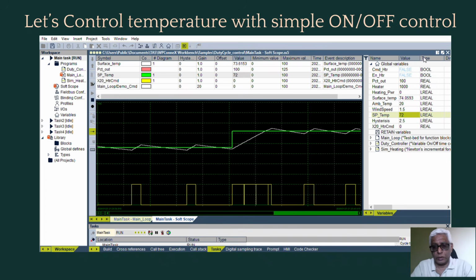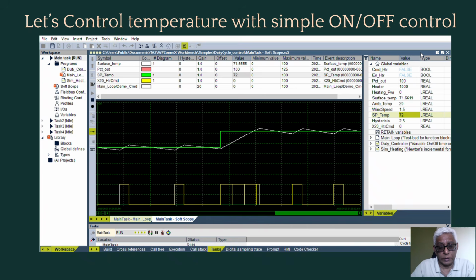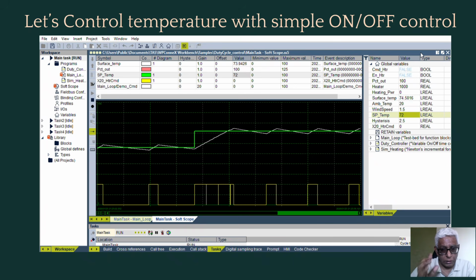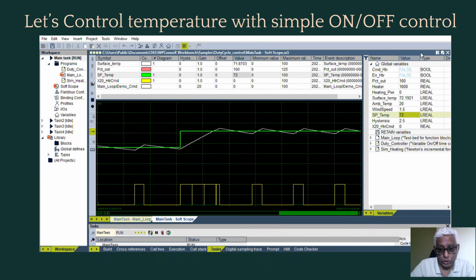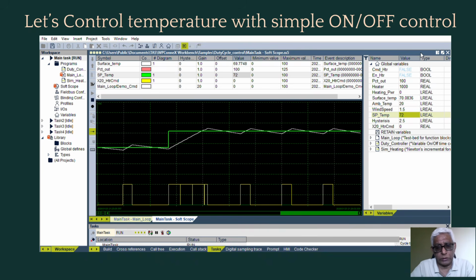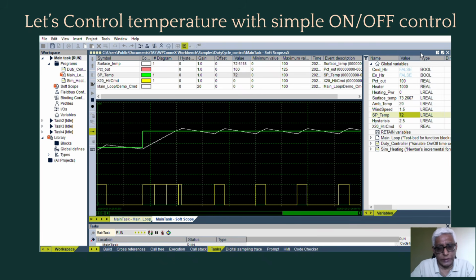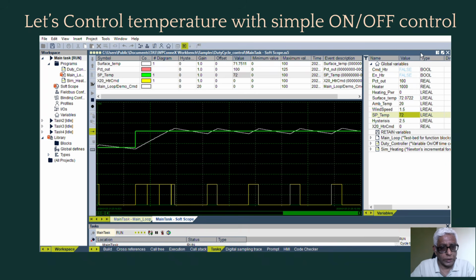Now see, this is after all a simulation and there are limitations. In real time, this kind of temperature control is very difficult, and the crossing of the set point on both sides is much larger than it is here, to the order of several degrees. You will never get good control on that. To get any kind of stability, you will find that the actual temperature swings in a wide margin above and below the set point. Most people keep the on-off control with no hysteresis on the upper side. That means most of the time it will be lower than the set point. Okay.